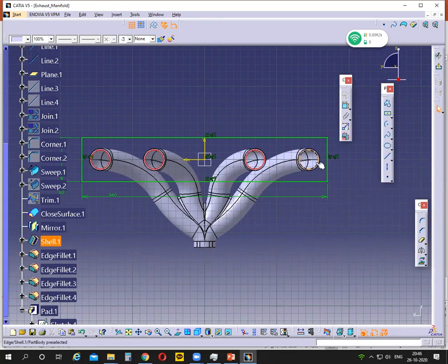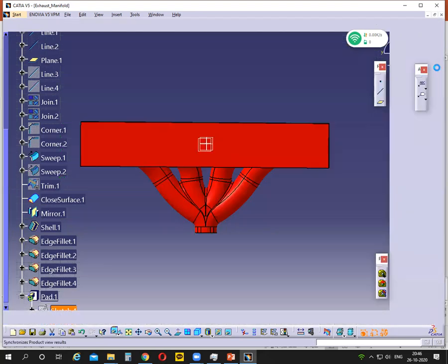You know, right? That option. So this one, project 3D elements. Otherwise, you have to make pocket again after making pad. Or you can draw a circle here and use the coincidence option with that edge. And the easy one is select the edges, the pipe inside edges, and use this option, project 3D elements, only one time, okay? So yellow color you can see, right? So I already projected.